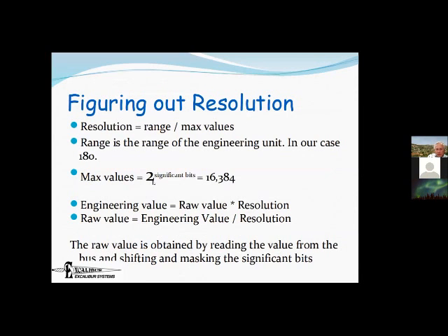Okay, so what is resolution? Resolution is the range, 0 to 180, divided by the maximum number of values. Now, the maximum number of values depends on the number of bits, and the math of it is 2 to the power of the number of bits. So 2 to the 14th is 16,384. And these are the formulas which most of you are absolutely not going to be interested in, so I'm going to move on.